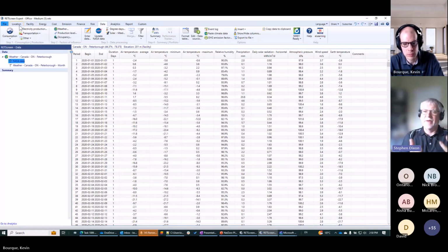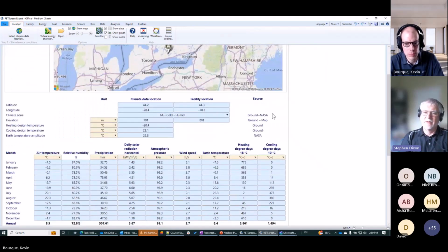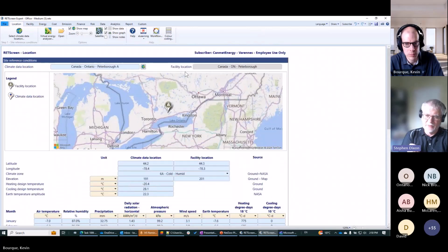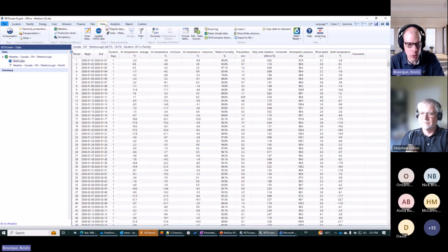So you can modify the basis for the climate data in the model, and then probably have closer results to your calibration. Closer, but don't go crazy. I always say plus or minus 5 to 10% on those numbers is probably reasonable. So, lots of stuff here, eh?